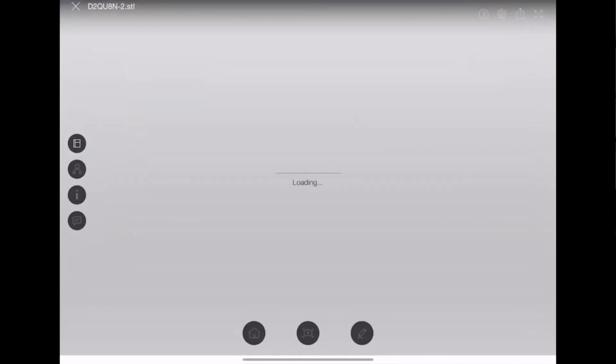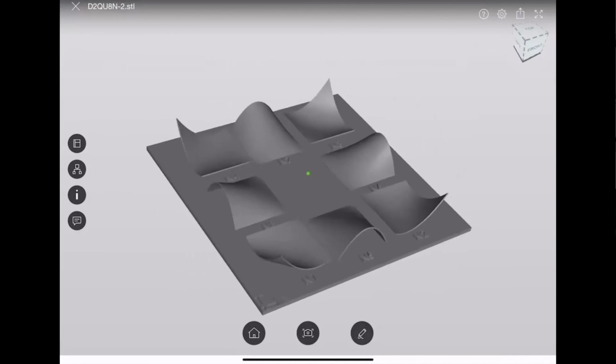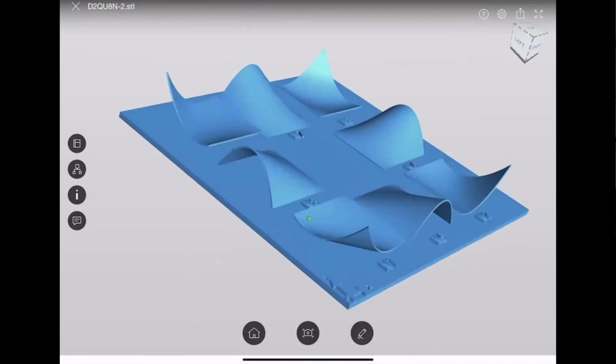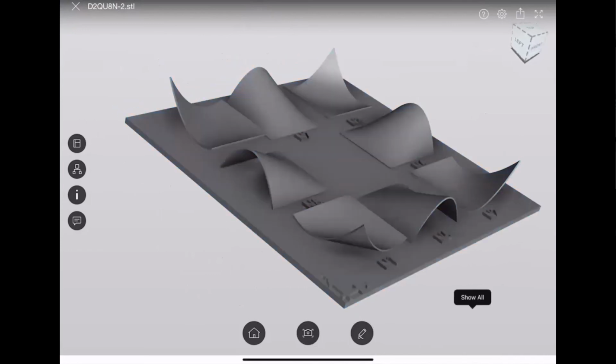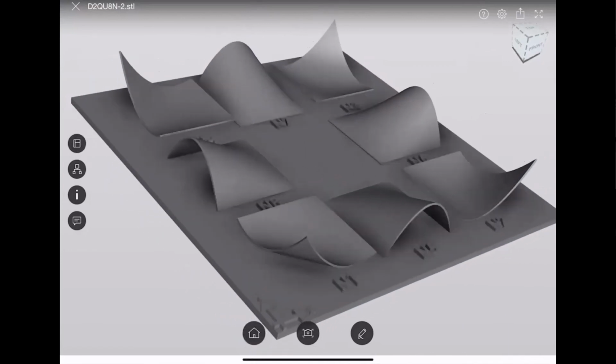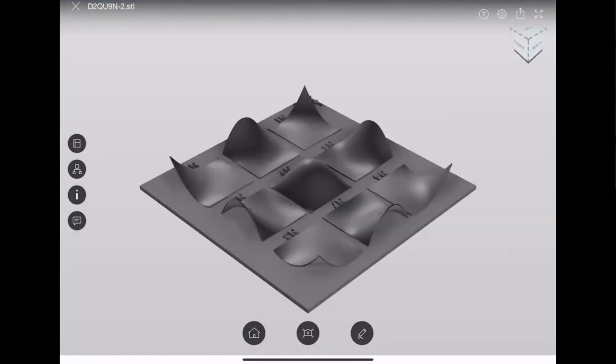If you have that 8-noded element, again, we play the same game here. Now you have these shape functions, again, the order of the nodes is the same way that we numbered them. So N1 is the lower left corner, N2 is the lower right corner, and so on. And these would be the way that those 9 shape functions look like. And then you can imagine exactly how they make the edges of your elements or the shape functions. And then we play this game also for this 9-noded one.